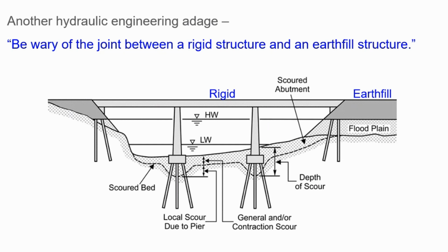Typically, you keep the pile cap lower than the bed level. These are types of scour that can occur. One of the issues at the moment in estimation of bridge scour is how you combine these various scour aspects. And so CDOT, the Colorado DOT, at the moment doesn't bother about scour. It runs the piers all the way down, piles all the way down to rock. So you don't have to worry about scour.